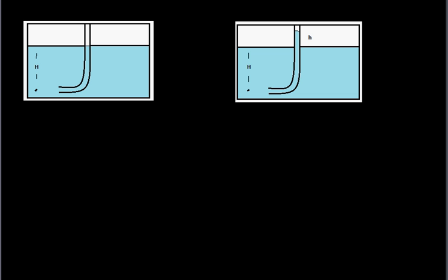Okay, so just came back from a short break. Going to explain what a Pitot tube is. On the left here, this picture on the left, we have a Pitot tube in a stationary position, and then the Pitot tube on the right is in motion. Pitot tubes may be used on a boat, let's say. If you imagine that this is the bottom surface of the boat, and there's just a little tube that sticks down, the Pitot tube is used to determine the velocity of the boat.